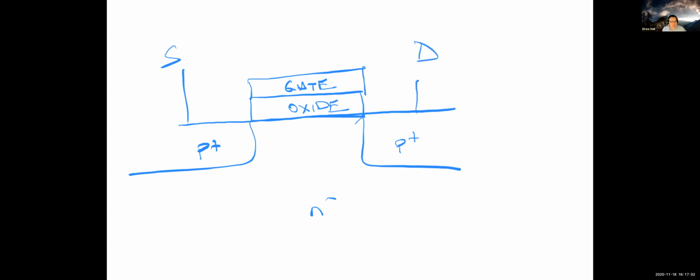All right, so your question is that I gave you that the oxide capacitance was something, I don't remember the exact number, 15 femtofarad per micron squared, and that the overlap capacitance was 1.5 microfarad per micron. And your question, very astutely, is that these aren't capacitances. They're actually normalized capacitances to the area, okay?